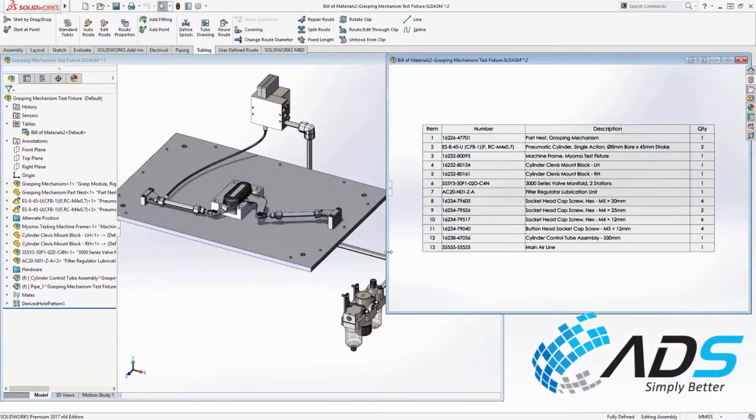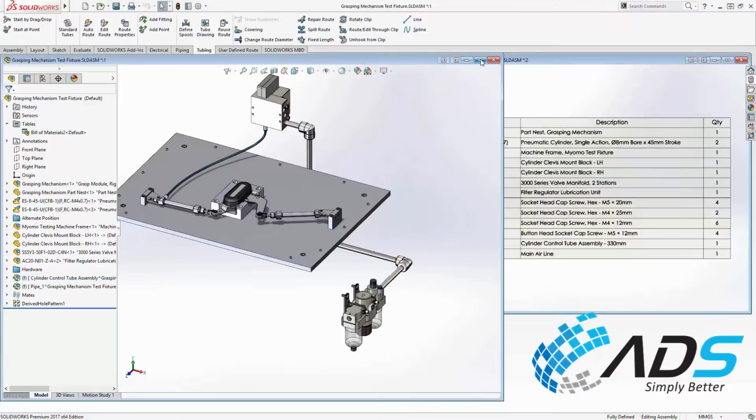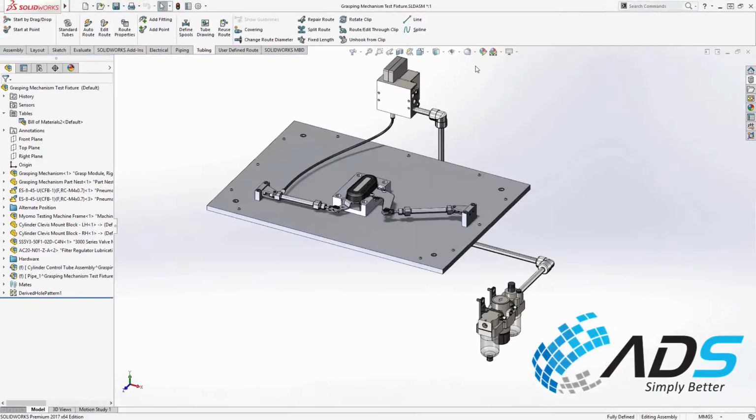You can see both the previous pipe route we just created and also the existing hose assembly, and as expected, they both have a quantity of 1. The reason for mentioning this is there are times you want to reuse a routed assembly. However, historically, due to the nature of how they're created, this wasn't possible. Now, however, in SOLIDWORKS 2017, you can reuse routed assemblies.